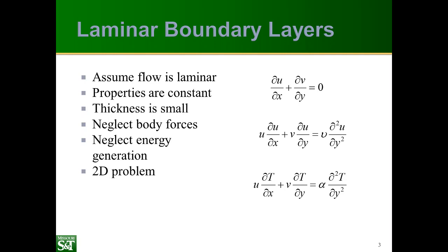Now, since we've assumed incompressible flows, you can see that the continuity and momentum equation don't have any dependence on temperature except through the fluid properties, but that's usually small, the kinematic viscosity. So for incompressible flows, it's convenient because you can first solve the velocity and continuity equations for the velocity field and then solve the energy equation for the temperature field. So it allows us to what we call decouple those equations.